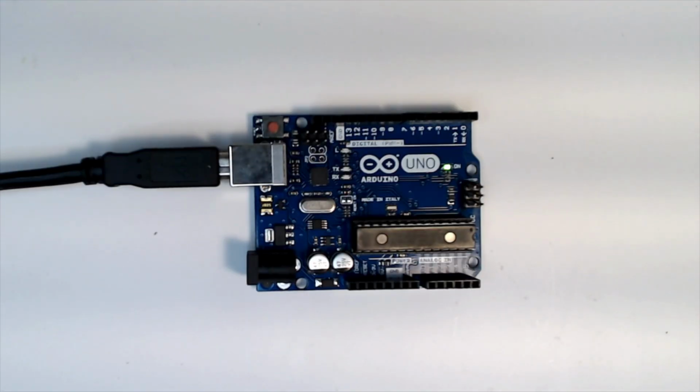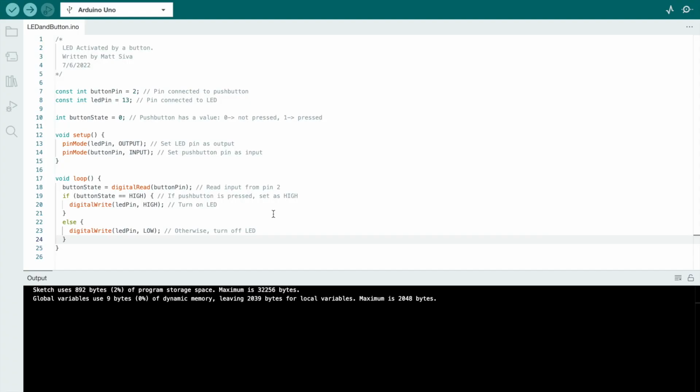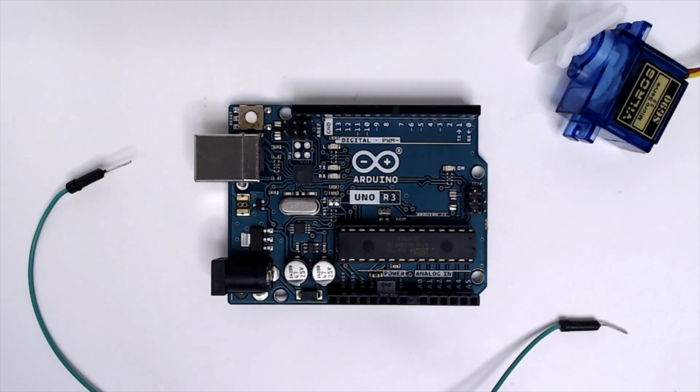You can also tell if your code is being received by the Arduino by checking two lights on the board labeled TX and RX. TX stands for transmission and lights up when the Arduino is sending data. The RX stands for receive and lights up when it receives data. However, it's important to note that the TX and RX lights on the Arduino board only indicate if data is being sent or received through the board, but they don't indicate if the data transfer is successful. So you should always double-check the IDE to make sure everything is working properly. The Arduino IDE can seem a little overwhelming at first, but with practice and some guidance, you'll soon be a pro at using it to create all kinds of cool projects.